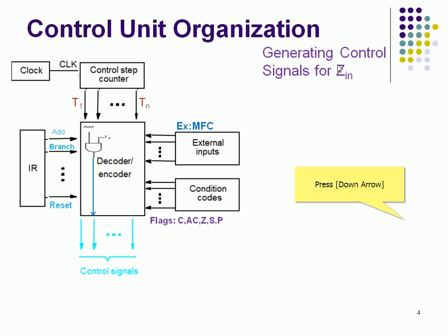So in order to do so, how is this signal going to be generated? For example, we can see Z-in is equal to T1. A clock pulse is required, right? This is going to help us generate a separate signal for each operation. One is essential, clock pulse T1 is essential, and T6 ANDed with add. Why can T6 be ANDed?